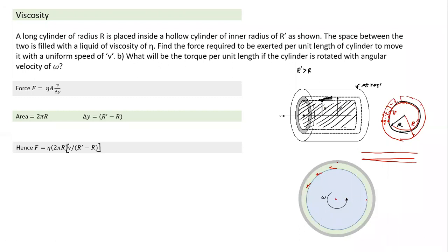Let's see that part. If I take a small piece of the cylinder, now this will be like a plane surface. This area is d theta, and its perpendicular direction is 1 unit here. So what is this area equal to? This becomes like a flat plate, moving on the surface, and in between the velocity is varying from 0 to r omega. V is equal to r omega. How much force will act? If I take the area here, the area will be equal to r d theta.